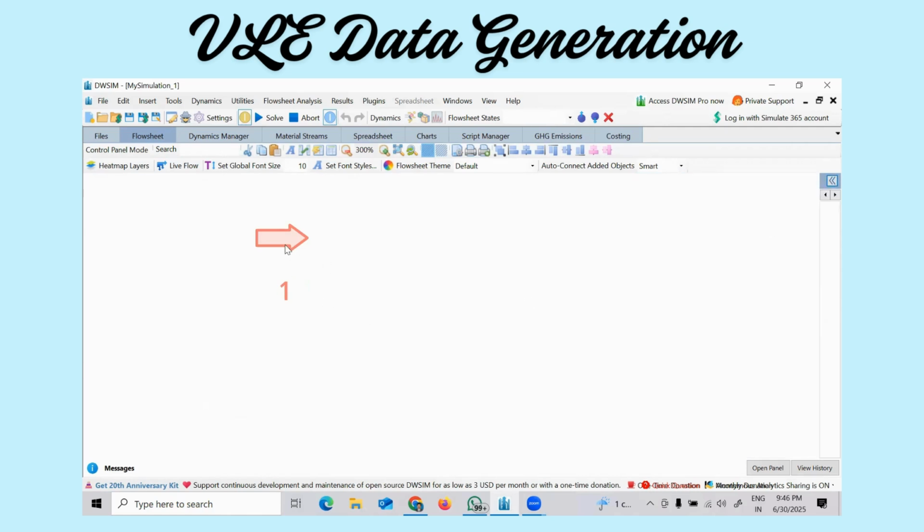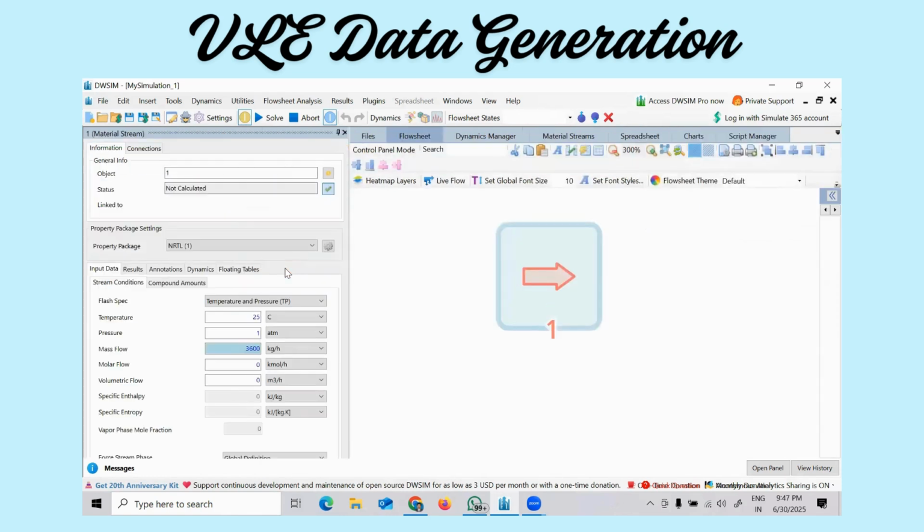Okay. Now see that this particular stream is known as stream one. It is named stream one. Now if I double click this, the stream conditions open, that is known as material stream. I name it feed, or feed stream, let us say feed, and that is a shortcut, ETOH plus H2O, so that we understand it better.